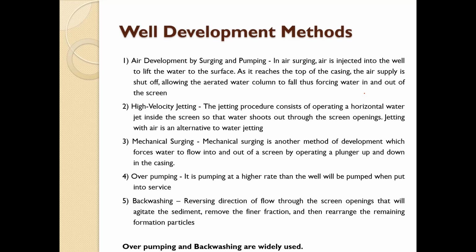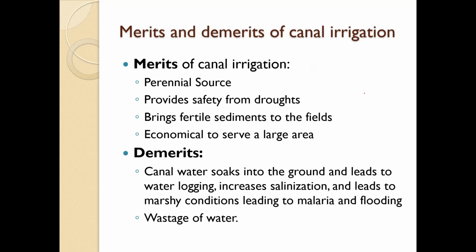Then overpumping. It is pumping at a higher rate than the well will be pumped when put into service. And backwashing, reversing the direction of flow through the screen openings, which will agitate the sediment, remove the finer fraction, and rearrange the remaining formation particles. Among these methods, overpumping and backwashing are widely used.